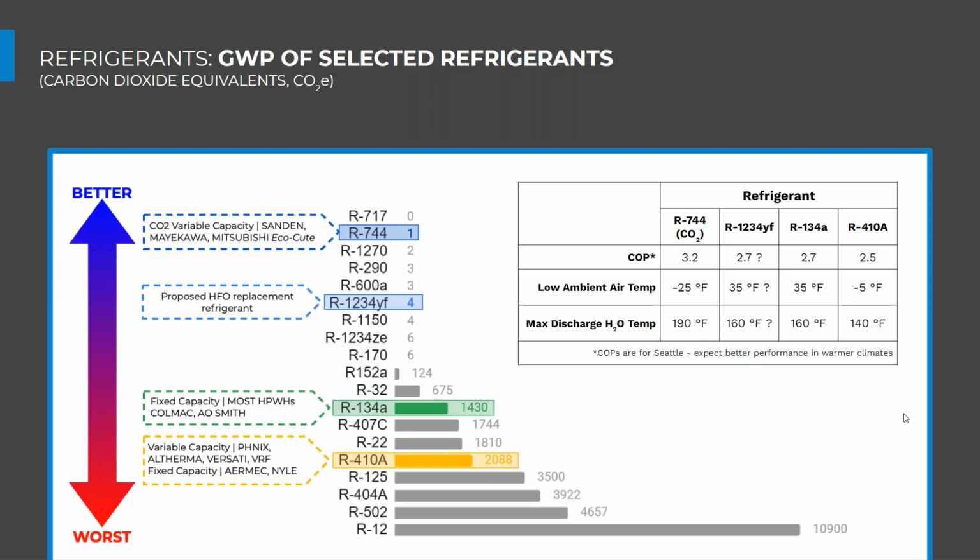And so although the manufacturer might rate our heat pump water heater at 70-degree air and maybe 120-degree leaving water temperature, at our actual design condition, we're going to be getting substantially less. So once you get that required heat capacity from the Ecosizer program, it's really important that you're sizing for the design day rather than sizing for the manufacturer's published point.